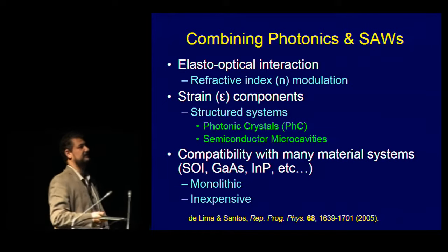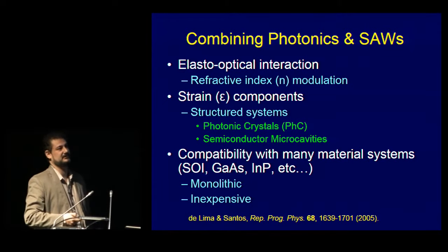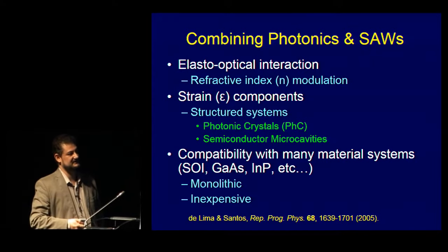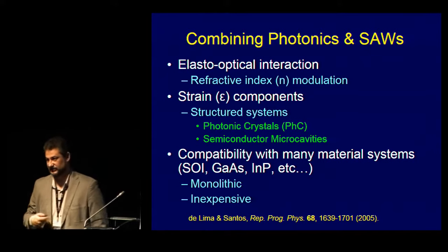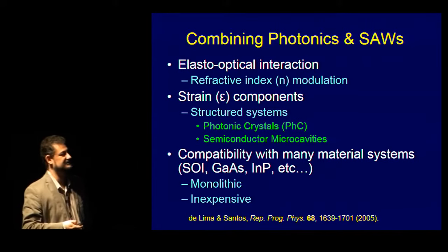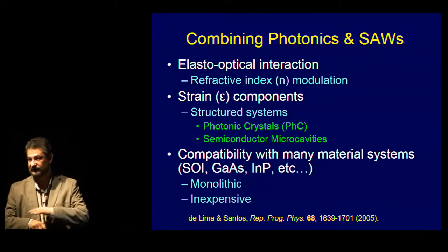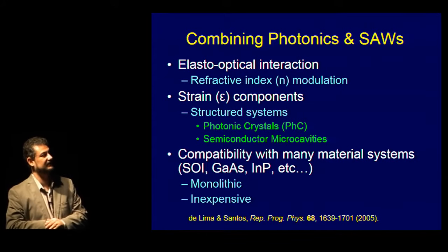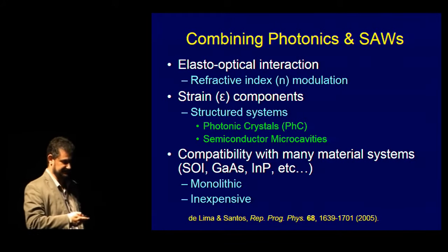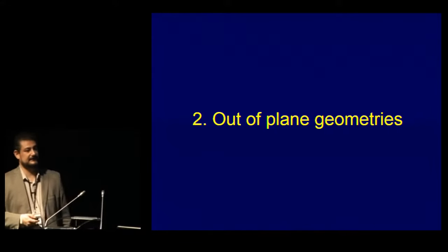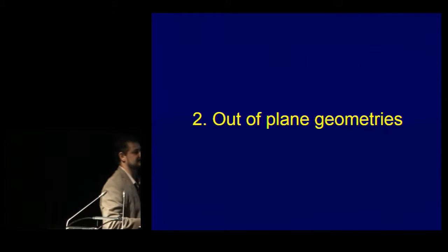From a technological point of view, it's interesting because it's compatible with almost every material. It's monolithic and it's very inexpensive. Someone may say, okay, but systems like SOI, they are not piezoelectric, so how can you say that they're compatible? But we can just put on top of the system a piezoelectric overlay, and then we can generate our acoustic waves. Then our out-of-plane geometries.